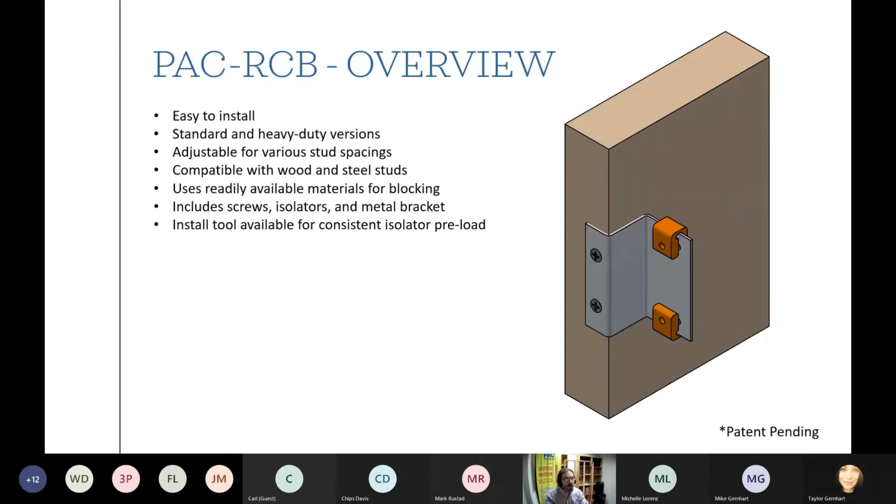So just an overview of it. It's easy to install. It's just a couple of screws. We have some install tools for it as well. We have standard and heavy duty versions designed for different load carrying capacities. It's adjustable for various stud spacings. I have one sitting next to me, and there are slots in this, so there's some movement so that you can get some fine adjustment once you mount the brackets to the studs.